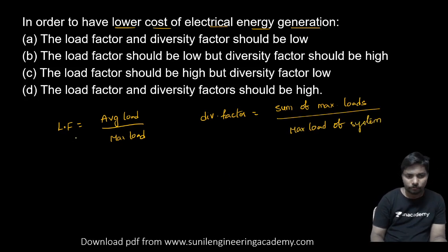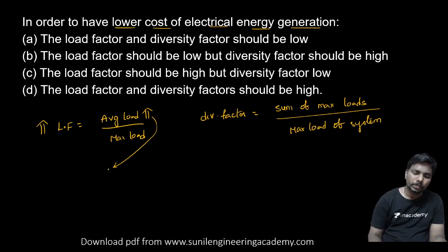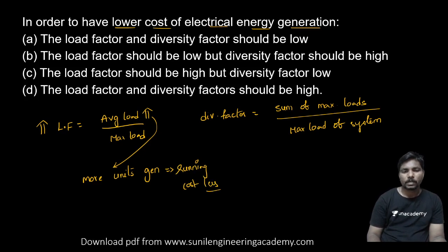If load factor is high, that means more units are generated. If more units are generated for the same amount of fuel, the running cost is less.